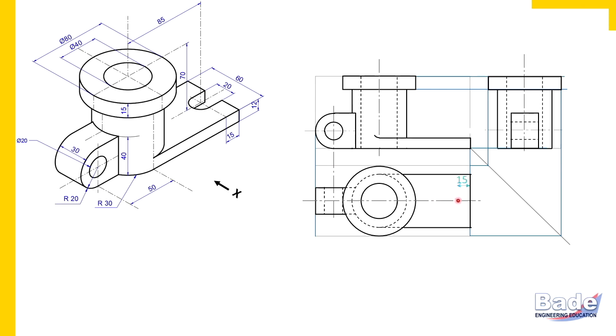Now we'll draw that slot in the plate. So this slot, its opening is visible from the top. So in the top view we are constructing that slot. Now to construct that slot, first the curved edge as usual. So this U-shaped slot, first its curved edge, the semicircular edge. Check where is its center. So extreme right 15 millimeter on the axis of symmetry. So I measured 15 millimeters, and on the axis of symmetry, this is the center line, and I have located the center.